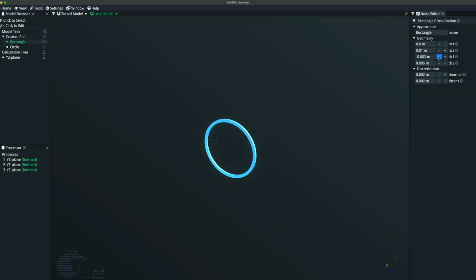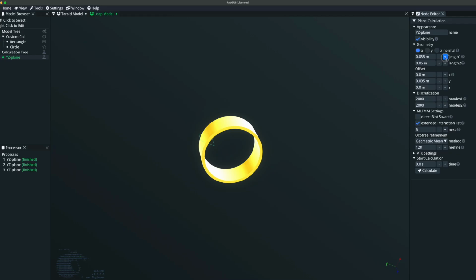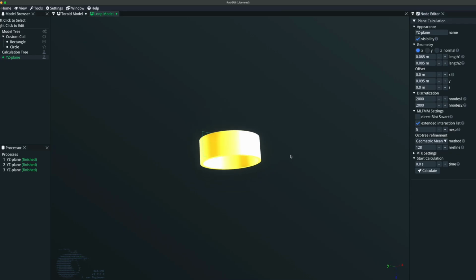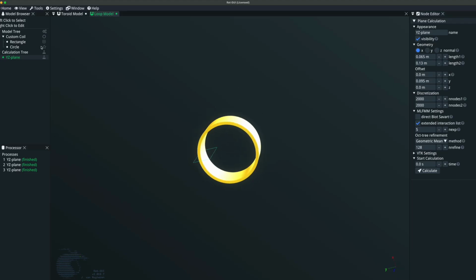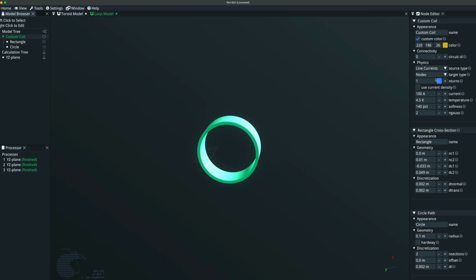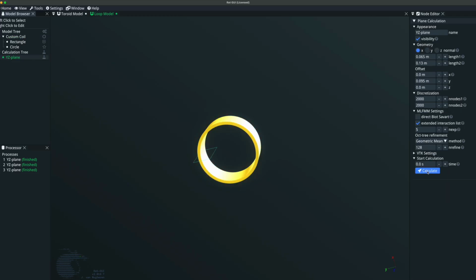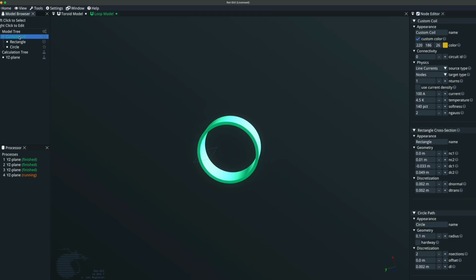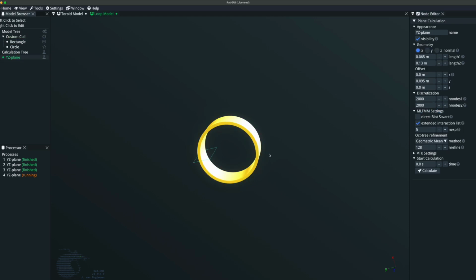Oh, no, I actually meant longer. Yeah, so the solenoid becomes a bit longer. We also have to grow our XY plane a bit so that it's sticking out. So this would be a reason to use Soleno type elements, but by default, let's say we're using line currents. Maybe I should have put fewer numbers here again, because I'm not sure if we need all the target points. I'm going to cancel this.